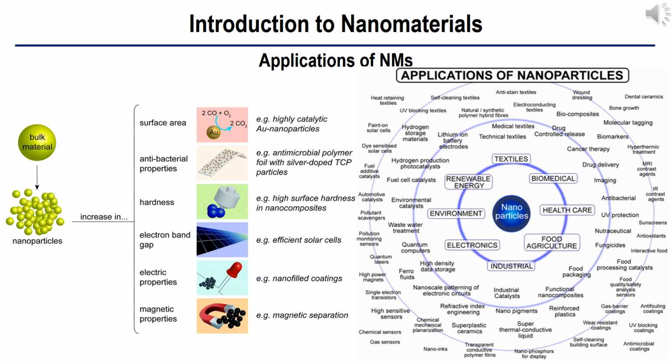The performance of a fuel cell electrode can be optimized in two ways, by improving the physical structure and by using a more active electrocatalyst. A good structure of electrode must provide ample surface area, provide maximum contact of catalyst, reactant gas and electrolyte, facilitate gas transport and provide good electronic conductance.